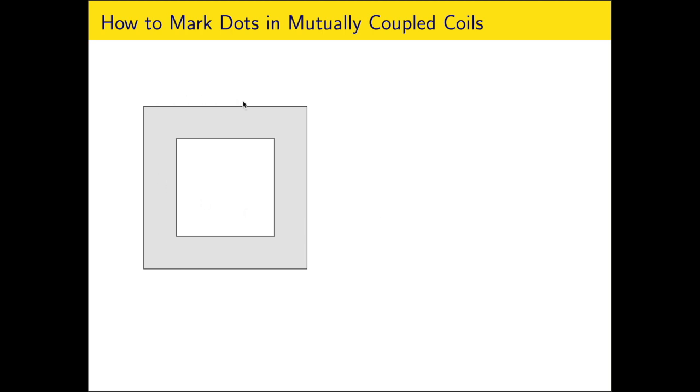So this is a core. On this we are placing the winding. So let's say one winding is placed which has two terminals, A and A dash. Now we are giving the current, and the current is directed likewise. Now if we apply the right hand rule, the direction of flux will be upward.